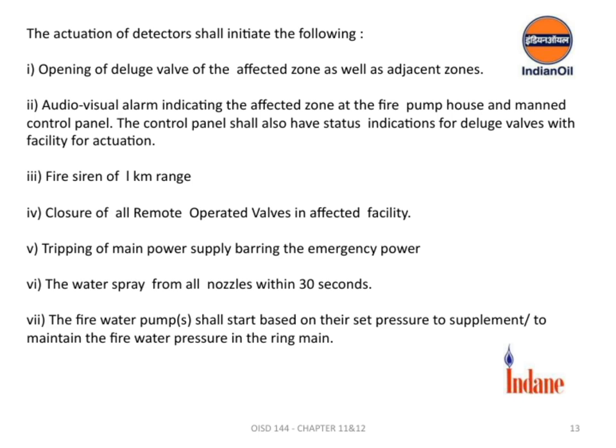Simultaneously, all remote-operated valves in the affected facility will close to contain the fire and prevent further damage. The main power supply to the facility will trip, except for emergency power, to isolate electrical sources and reduce risks. Within just 30 seconds, water spray will be released from all nozzles, providing immediate suppression around the affected area. Finally, the fire water pumps will start up based on their set pressure thresholds, helping to maintain the water pressure